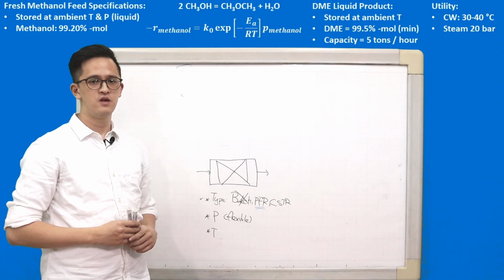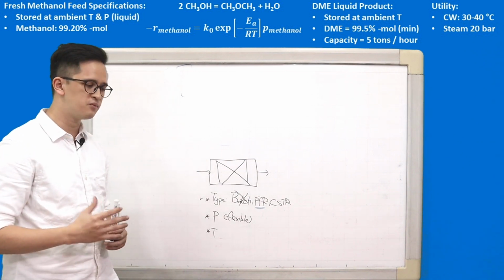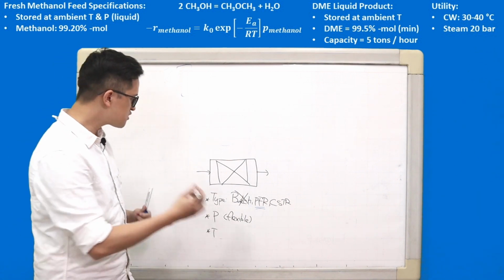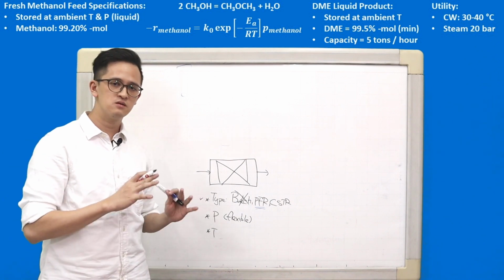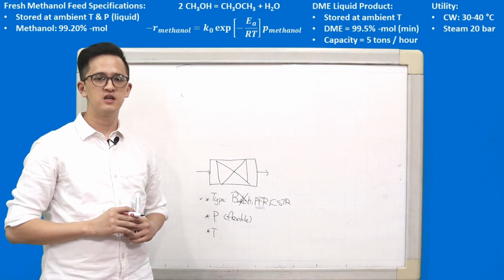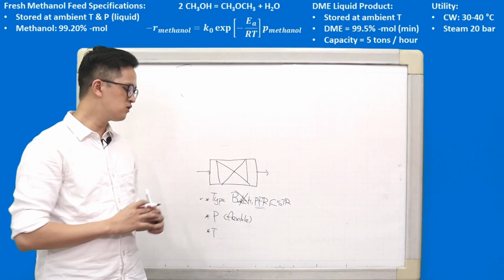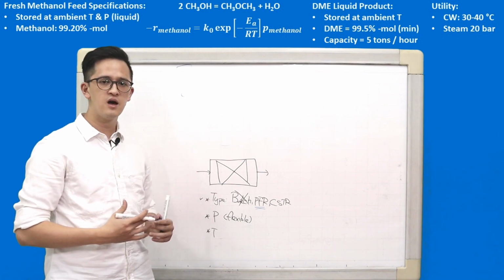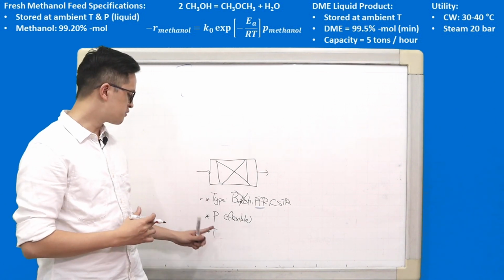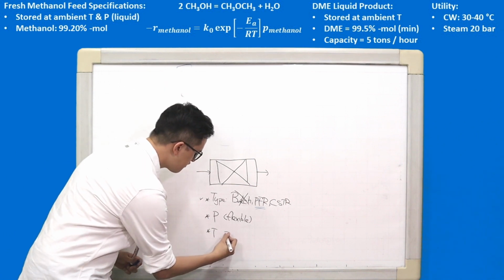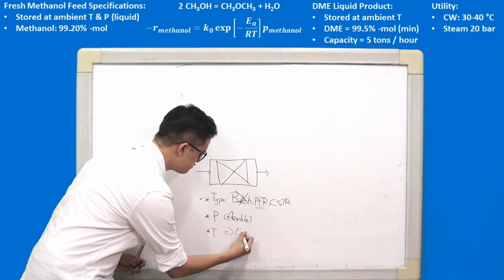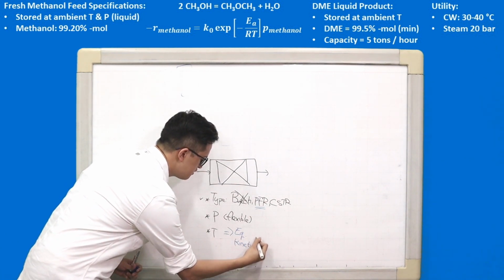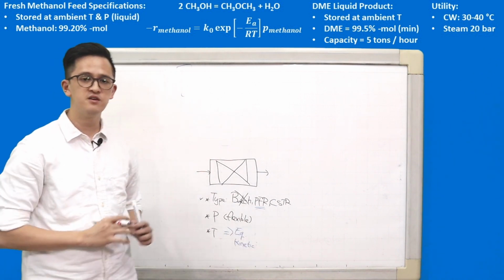of the reactor. And actually, if you look very closely at the previous video about the case definition, we already gave you a hint that the temperature has to be limited at a certain point to prevent any catalyst deactivation. But before we go to that number, it's important for us to remember, for an exothermic reaction, how the equilibrium will shift if the temperature changes. Okay, so for every reaction, we have to consider the equilibrium and the kinetics. How will it change specifically for our case study?